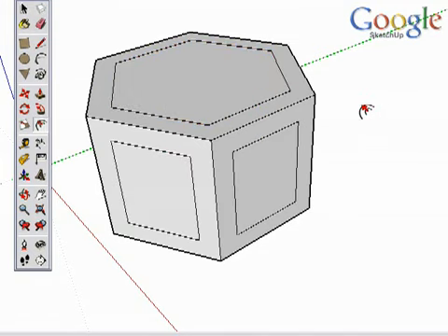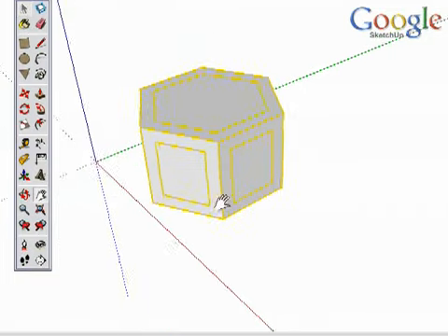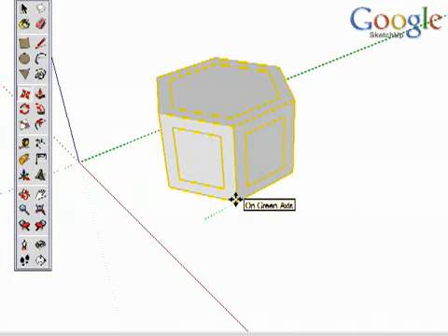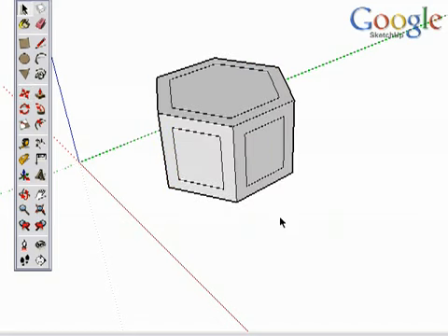By now, you should have a good idea of many ways to be accurate in SketchUp. You can also specify exact distances when moving objects and exact angles for rotating objects, all with keyboard input. Another way to be accurate is to create guides for you to reference.